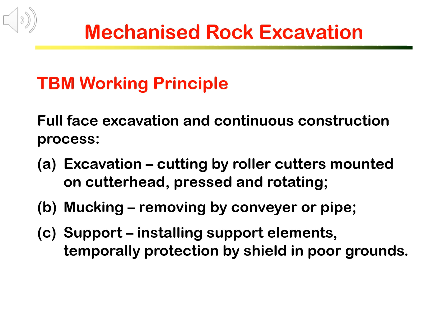For shield TBM, temporary support is by the shield, and permanent support is by the concrete segmental ring installed inside the shield. When the TBM moves forward, the concrete segmental lining then supports directly to the ground.